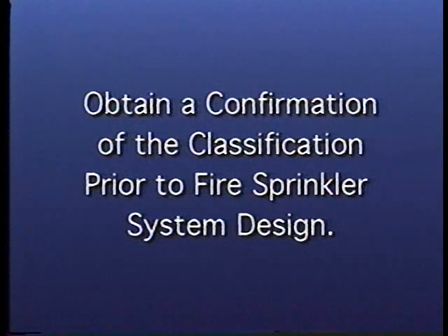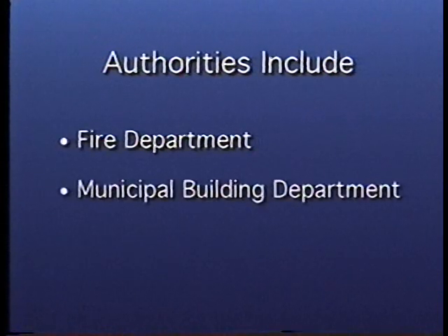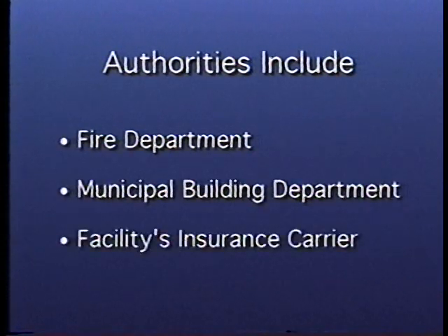Defining the hazard classification in some occupancies can be subjective. It is important to obtain a confirmation of the classification from the authorities having jurisdiction prior to the preparation of the fire sprinkler system design. The authorities might include the fire department, the municipal building department, and the facility's insurance carrier. There are several key design factors that are affected by the classification of any building or facility.